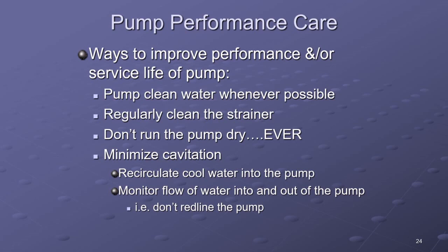Minimize cavitation, so recirculate cool water into the pump. That's why we have a bypass on every engine anymore. Monitor flow of water into and out of the pump. Don't exceed your ability to get water in is the key. That's really what's going to cause cavitation, is you're pushing more than you're getting in. And we'll go into cavitation and what it means and what it looks like here in a bit.